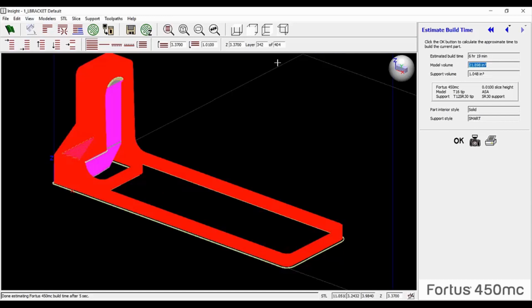Well, that's absolutely correct, but because we're not purging, we're actually saving more material than we're using by building the structure out of the model material itself. So we'll see all the numbers in the table at the end of this, but that represents a 7.5% material savings and a 27% runtime savings just by that quick little change.